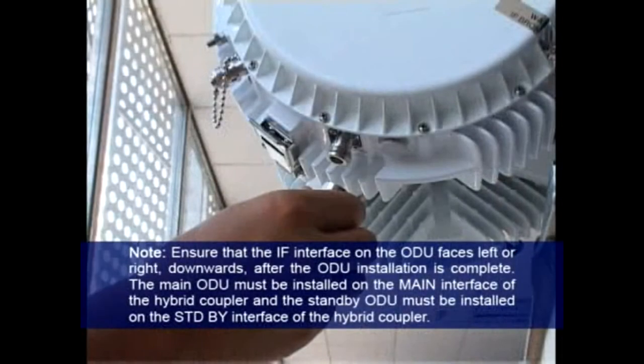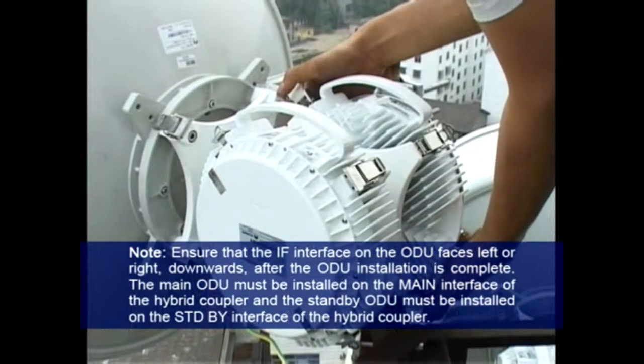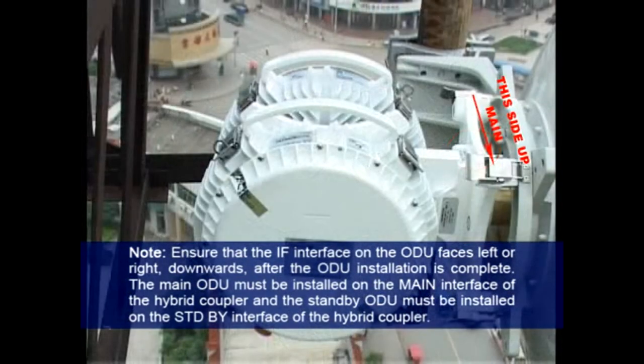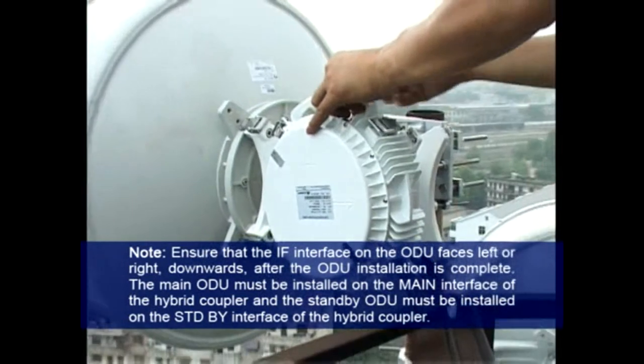Note: ensure that the IF interface on the ODU faces left, right, or downwards after the ODU installation is complete. The main ODU must be installed on the main interface of the hybrid coupler, and the standby ODU must be installed on the standby interface of the hybrid coupler.